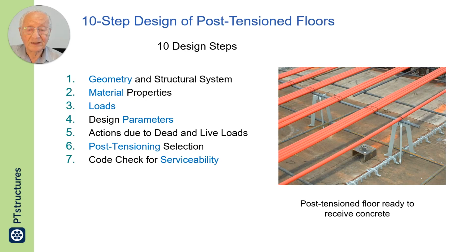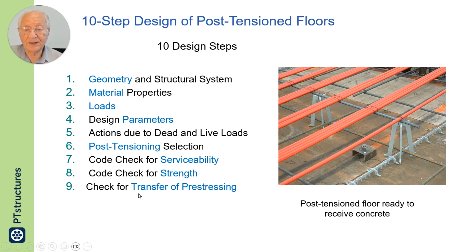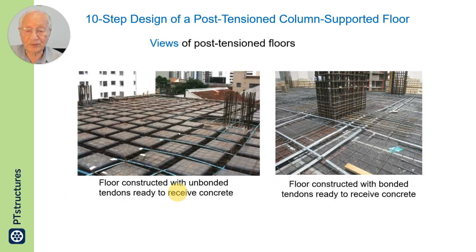We check the design for serviceability compliance of the code. Then we code check for strength after serviceability. Then we check for transfer of pre-stressing, at the time of jacking and applying the pre-stressing. Requirements will be explained. Then we go to detailing.